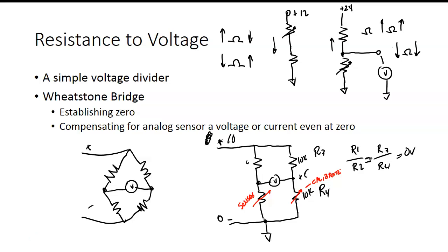In fluid power, you'll learn that there are two kinds of pressure gauges. One we call absolute pressure, and one we call gauge pressure. Gauge pressure takes out atmospheric pressure. So if you look at a pressure gauge and it's sitting at 0, when we know there's at least 14.7 psi at sea level, then that is gauge pressure, because somehow they've taken out atmospheric pressure, right?